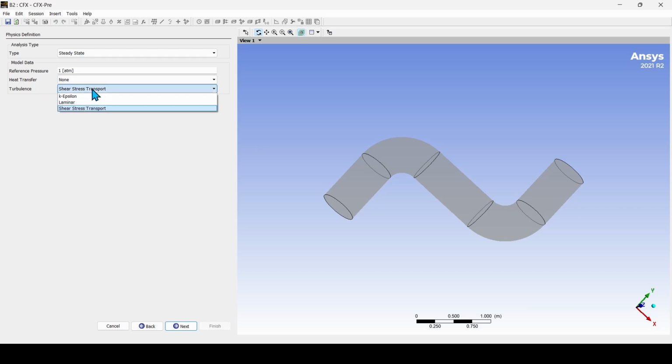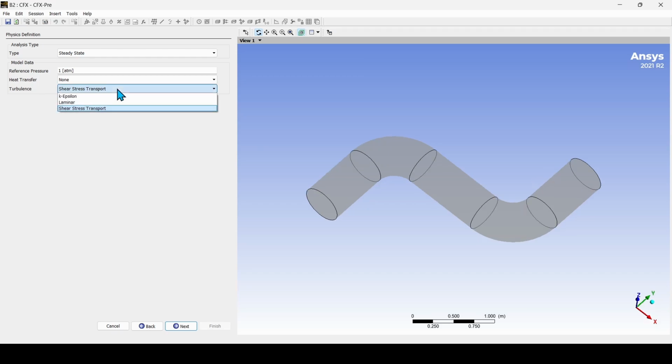We also have other turbulence models like K epsilon model and K omega model. The K omega model is suitable in near wall regions inside the boundary layer. And likewise, the K epsilon model is suitable for the regions far from the wall. While this shear stress transport model can be taken as the average of both models, the K omega and K epsilon model, this model of turbulence will have properties from both of the models.